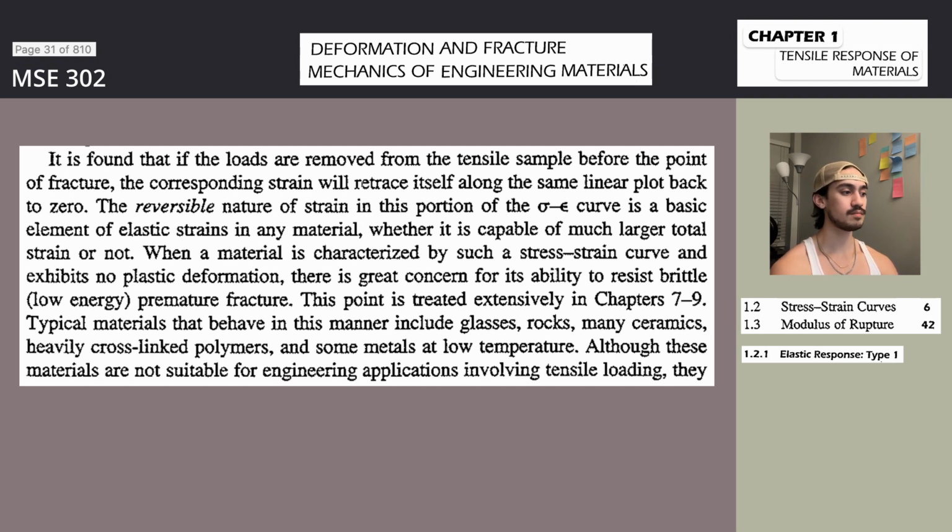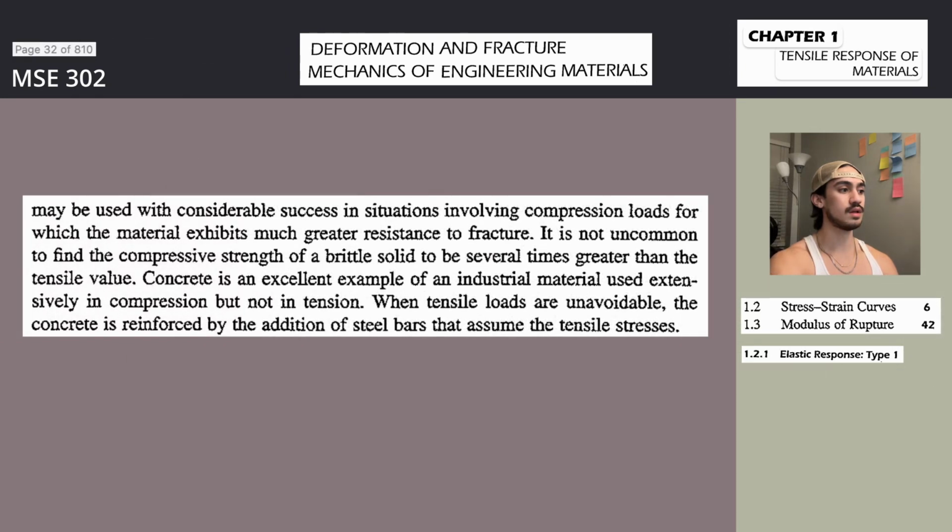1.2.1.2 Resiliency. The resilience of a material is the measure of the amount of energy that can be absorbed under elastic loading conditions, and which is released completely when the loads are removed. From this definition, resilience may be measured from the area under the curve in figure 1.1. Equation 1-18, where sigma sub max is the maximum stress for elastic conditions, and epsilon sub max is the elastic strain limit. From equation 1-7, we have equation 1-19.